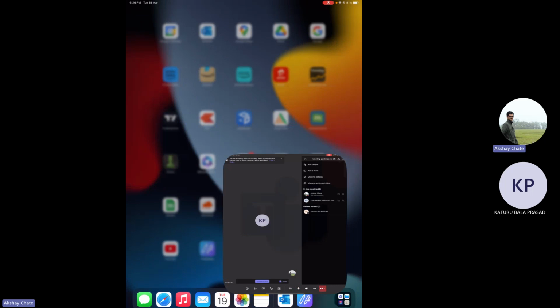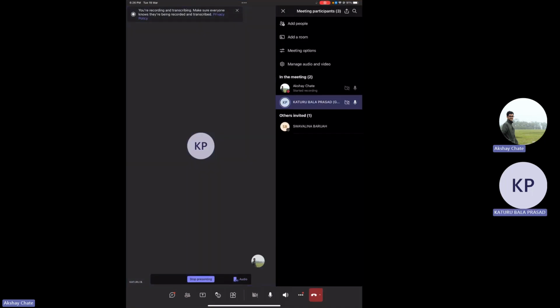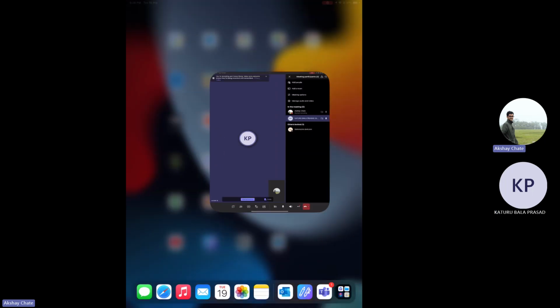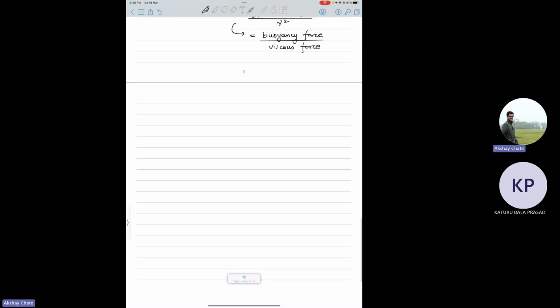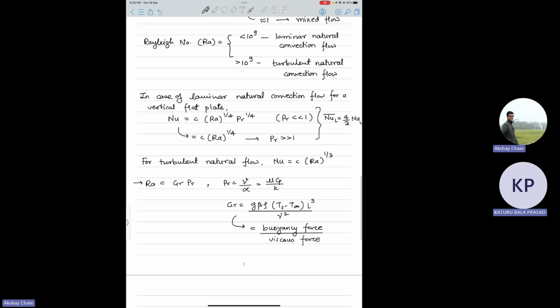Hello, excuse me, sir. Yeah, tell me. Sir, in the previous equation, I think you have written rho excessively. Please check it. Where are you saying? This last equation, the Grashof number. Yeah, what happened? It should be G beta delta T L cube by nu square only, right?